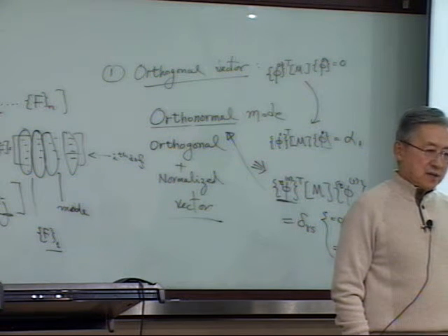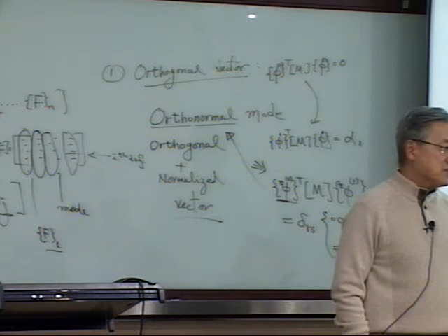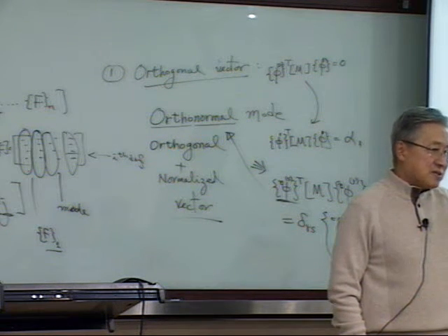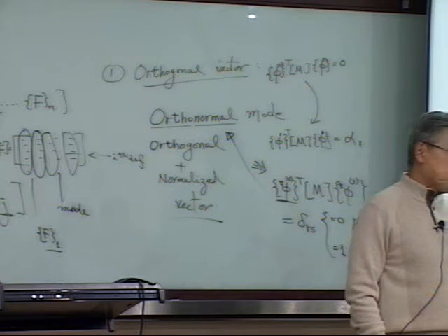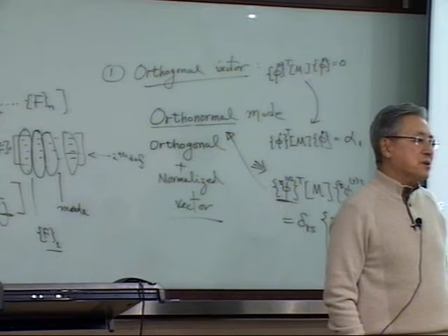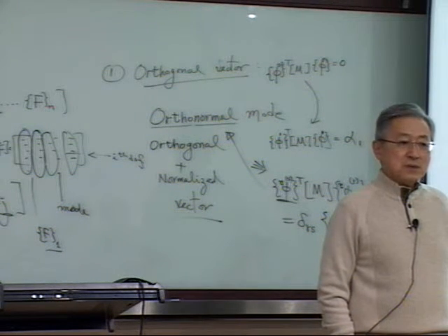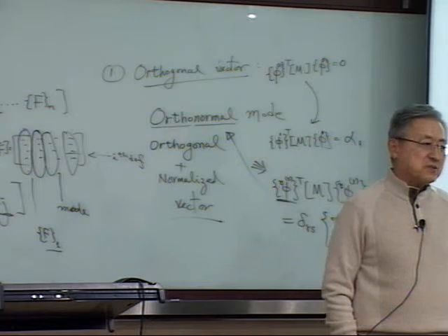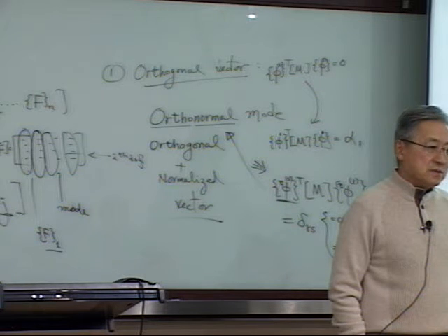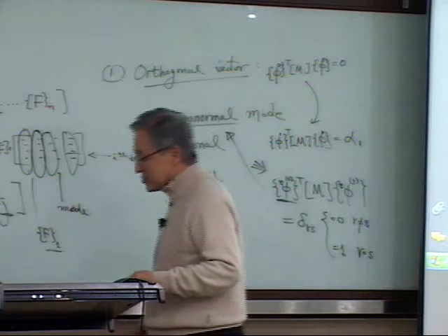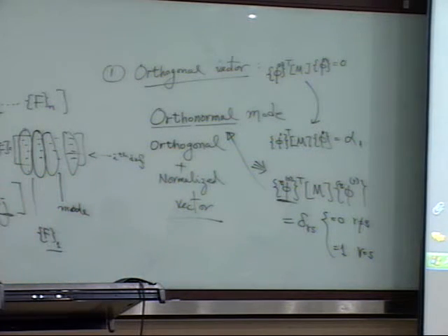Then how to say that? How can you say how many modes I should pick out? Because as you look at the modal participation factor, the lower modal participation factors are dominant. Maybe the first 10 modes, when you compute that, may be sufficient to include. So how to do that? That's what the so-called 80% criteria is, what this page is talking about.